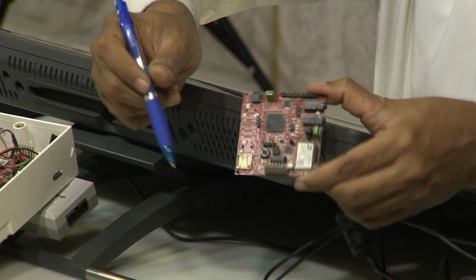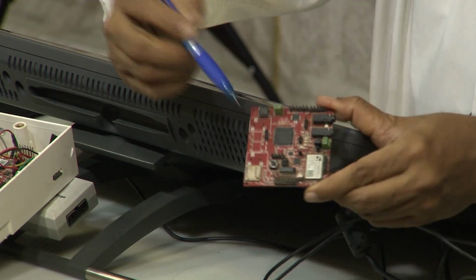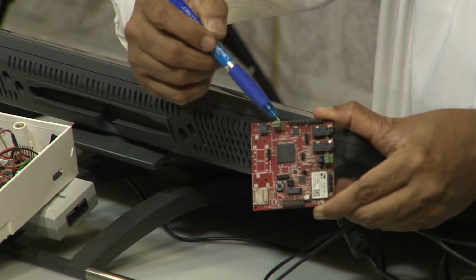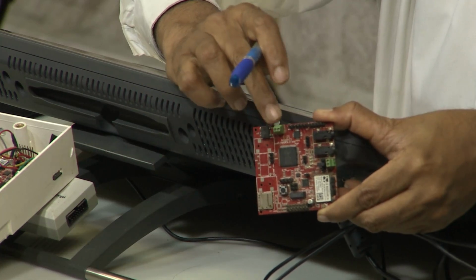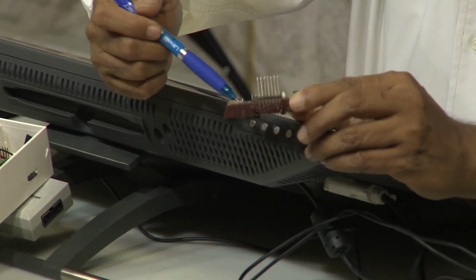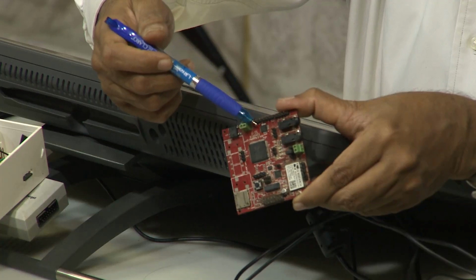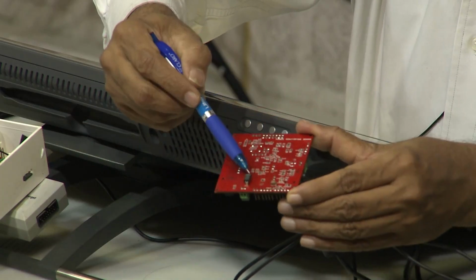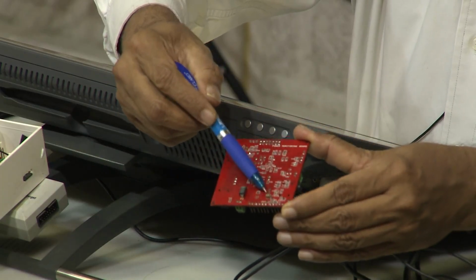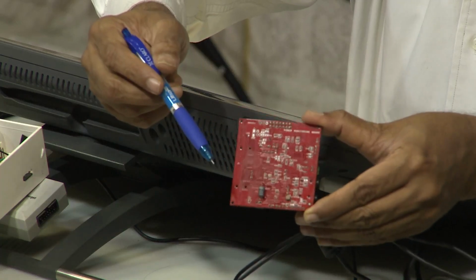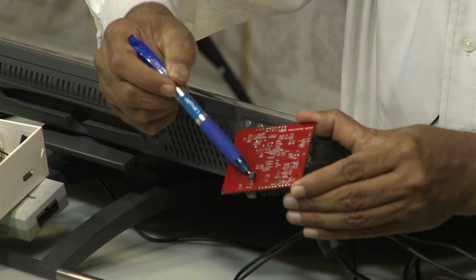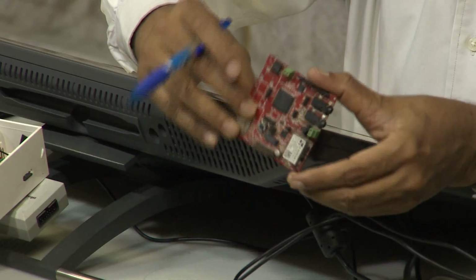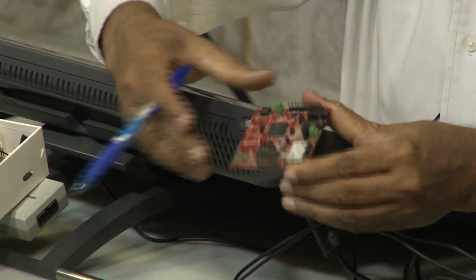Okay. Then what else do we have on this board? Obviously it has to be powered, so you need a rectifier chip. So you can see this is the rectifier chip. Then input, AC input is fed through here after stepping down in an appropriate manner. There is an LDO here. LDO's C in and C out capacitors are here. This is the C in capacitor, this is the C out capacitor. Let me hold it for you. This is the C in and this is the C out capacitors of the LDO, and what else.